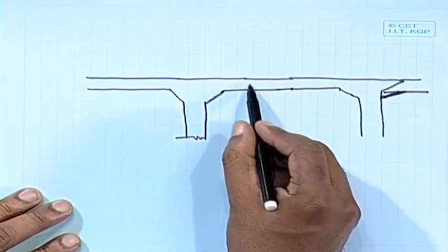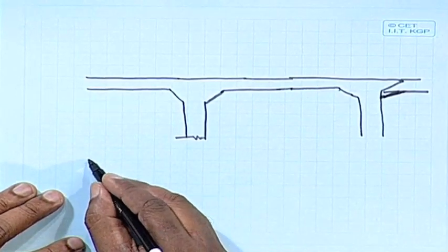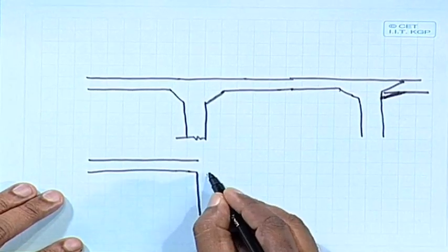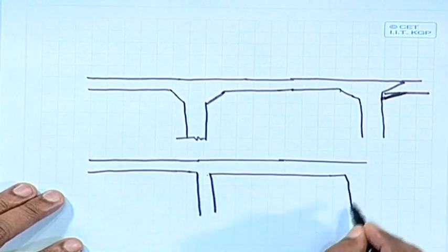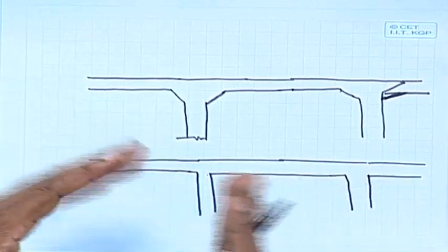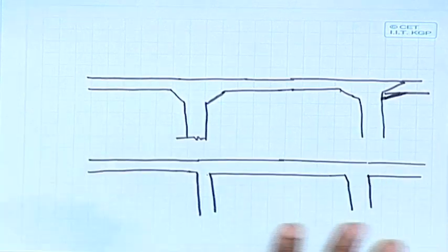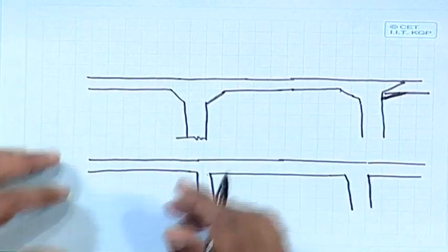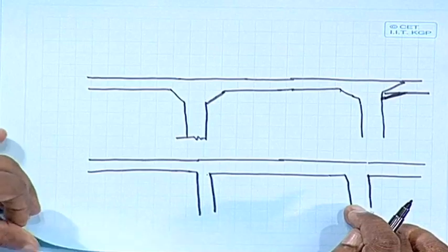So, this we can design as a flat slab. We can also take it simply as a flat plate, as if it is supported by columns only. There is no beam; it is just supported over different supports, and over that you are keeping one plate. Whereas here, you are making the column head a little bit bigger, and then over that you are keeping the slab or plate. So, this is your flat slab, and this one we call a flat plate.